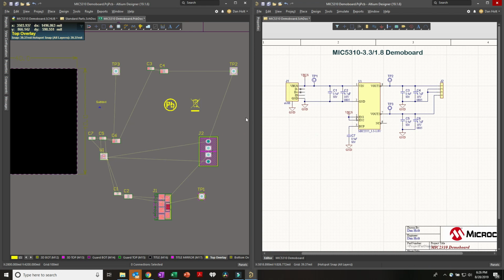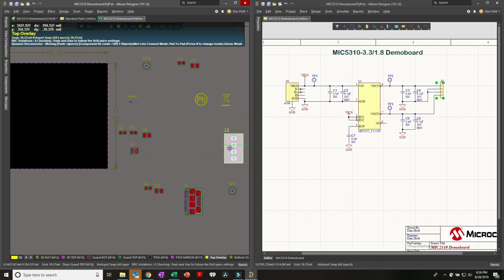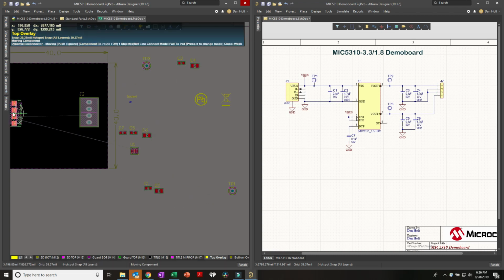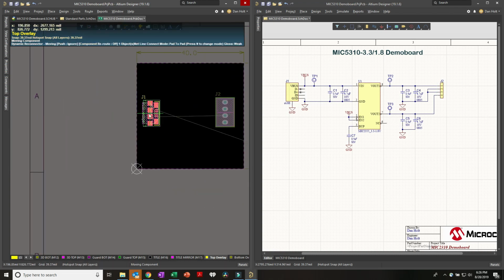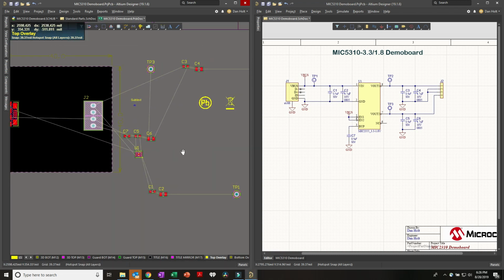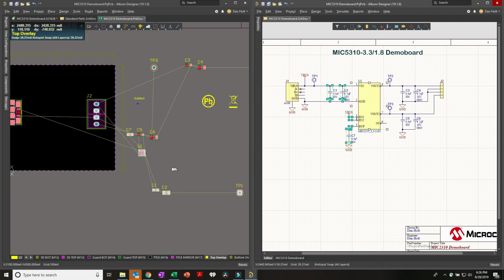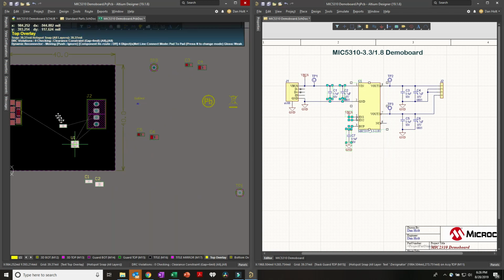So yeah, this really is helpful. So I'm going to take my output here, my input, and just start blocking these out. Just roughing these in. I'm going to take the IC and the input caps for a second, and this bypass cap, just take those 4 parts and drag those into here.